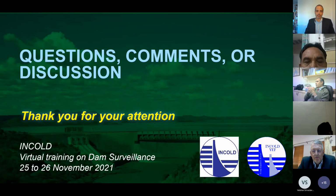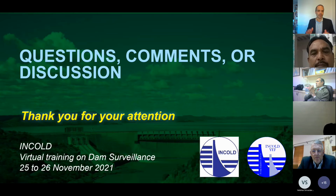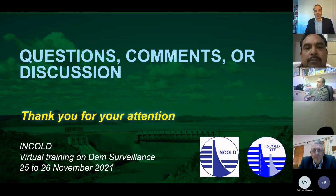But if it's really a huge problem, we have some good examples in the US and in Portugal as well. Eventually, you have to stop the overflow of water and really demolish that and rebuild it almost from scratch. But it really depends on the example. Also, the example in Africa of the scouring downstream shows stilling basins can be very critical in some cases. But I 100% agree with you, Manuel.